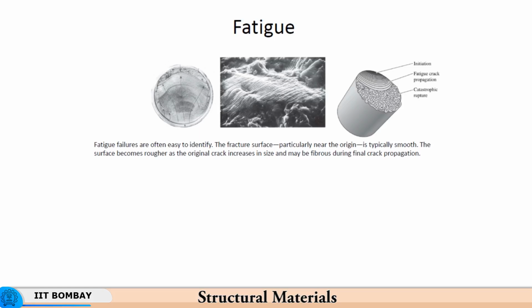So we have this fatigue crack which has been generated over here. In fact, there would have been a flaw over here, either a machine mark or a porosity, that is a blowhole or a pinhole or something like that, or even an inclusion at which the crack could start, and then it propagates with every loading and unloading cycle. So this fatigue crack propagation can be easily marked based on the striations, the so-called beach marks that are generated on the surface.